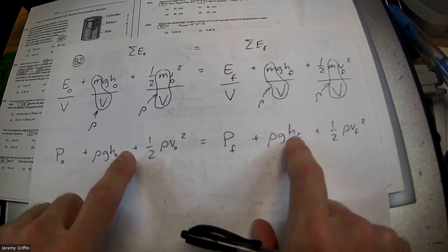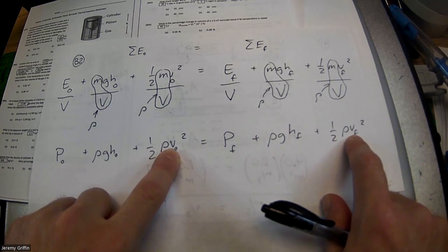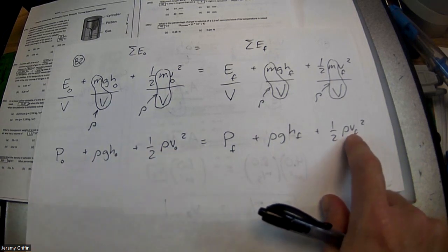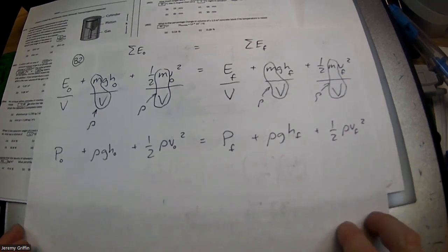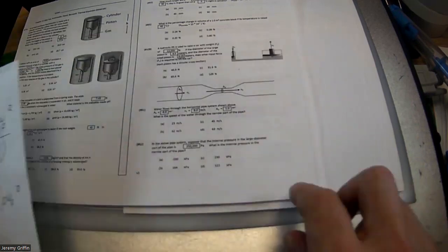And also something to do with how fast that fluid is moving. That v, velocity. The faster it moves, the less the internal pressure. You guys ready to apply some numbers? Let's take a look at this setup.